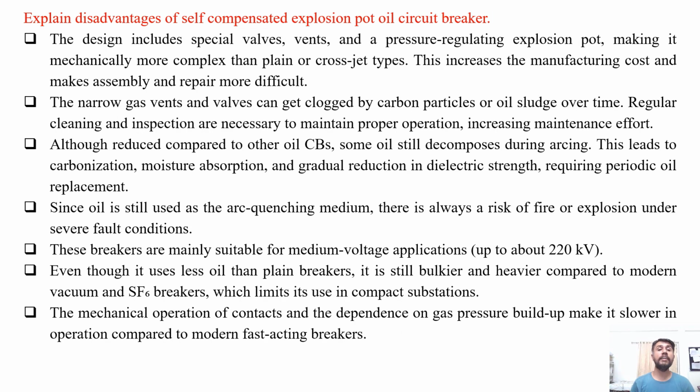Explain disadvantages of self-compensated explosion pot oil circuit breaker. So the design includes special valves, vents and a pressure regulating explosion pot, making it mechanically more complex than plain or cross-jet types of oil circuit breaker. This increases the manufacturing cost and makes assembly and repair more difficult.